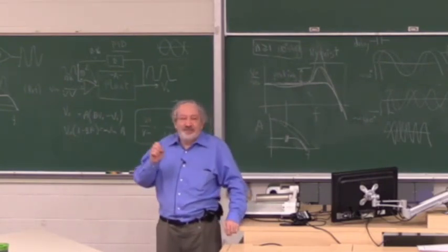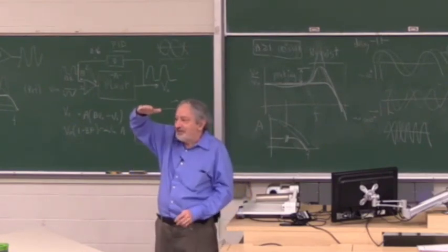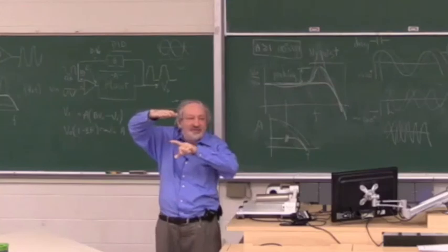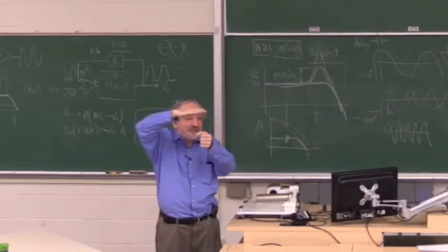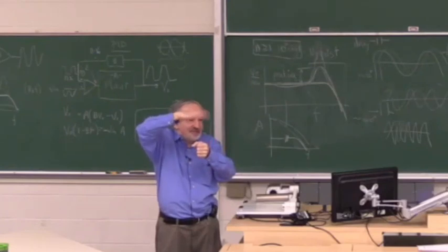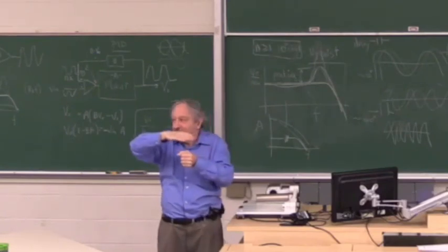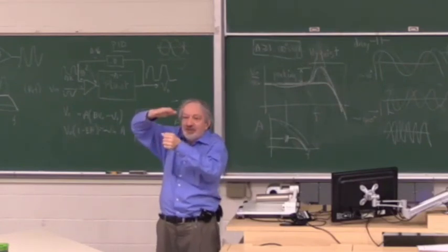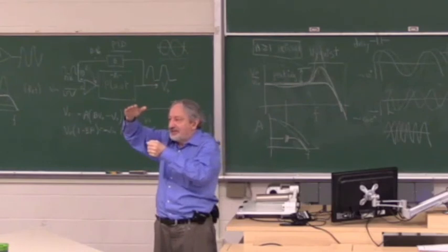Let's take a very specific example. You have a cantilever. You want to flex it with an electromagnet. So you have a cantilever, you put an electromagnet, the current bends the cantilever. But every cantilever has a resonance because it's like a tuning fork. Okay? So let's say you take a cantilever which resonates at 10 hertz, but you try to move it with a coil from 0 to 100 hertz.